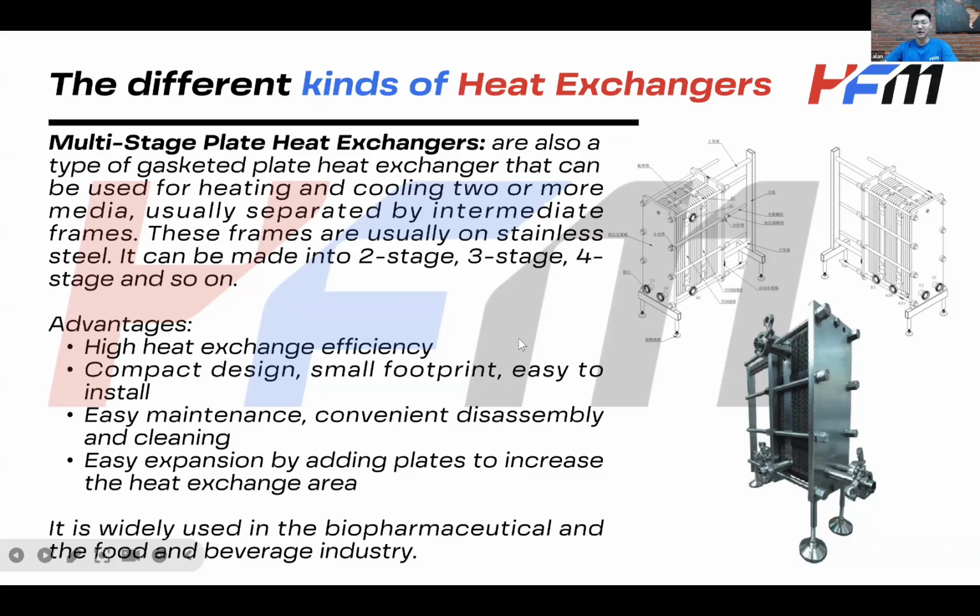And this type of PHE is widely used in the pharmaceutical and food and beverage industries. And there are some benefits to using this type of PHE. So it has high efficiency, compact design, and easy maintenance. And the last one is that it is easy to expand the capacity of this type of PHE by adding more plates into the units.